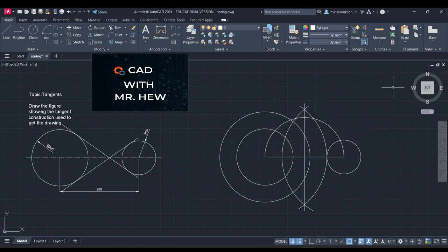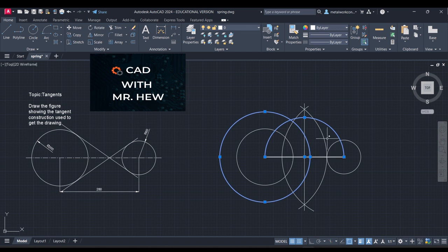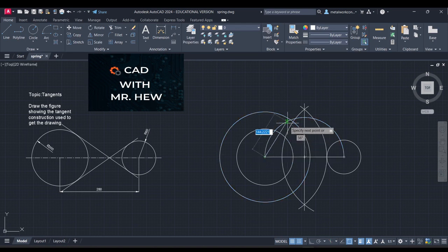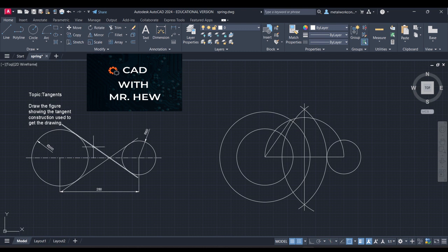Good job. Now, where this semicircle intersects the construction circle that you added the two radii for, the line drawn from that intersection to the center of the larger circle, this will be the normal. All right? Enter. Is that clear? So I'm saying, if you want this internal tangent, this blue highlighted one, you'd have to draw the semicircle above. If you drew it below, then what do you think would happen? You will get this one below.